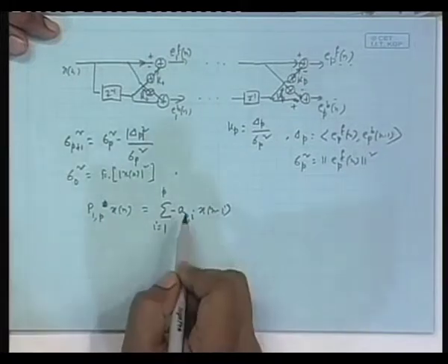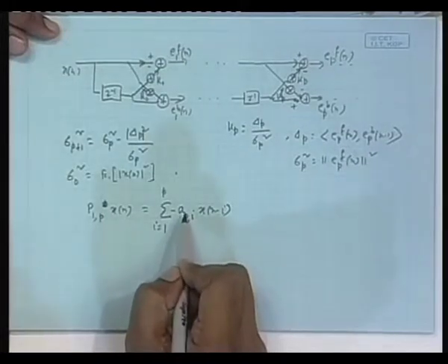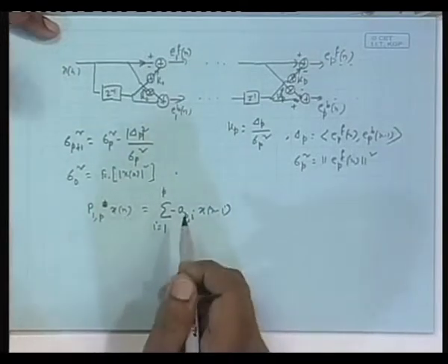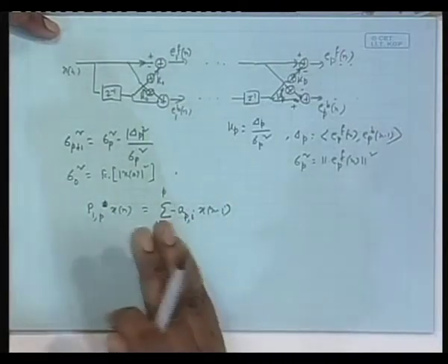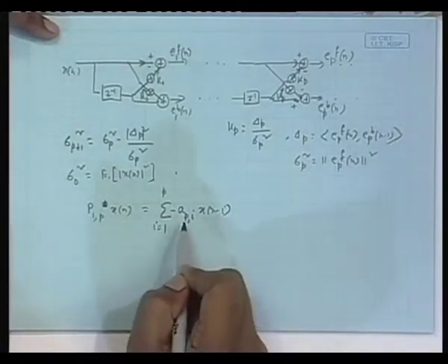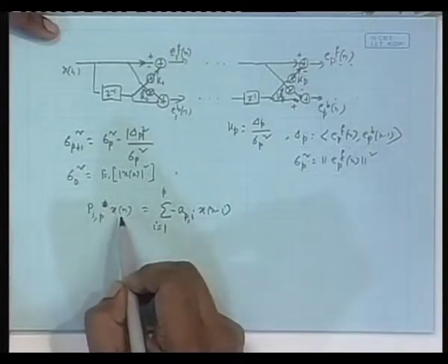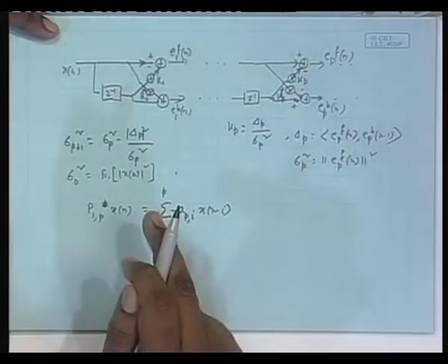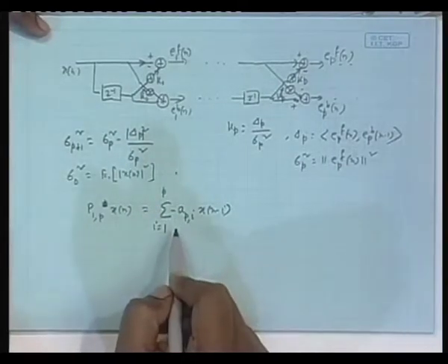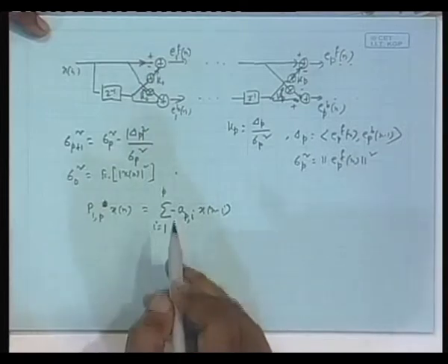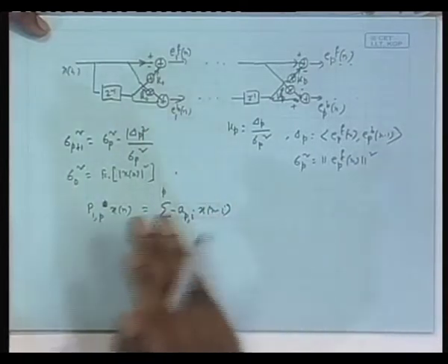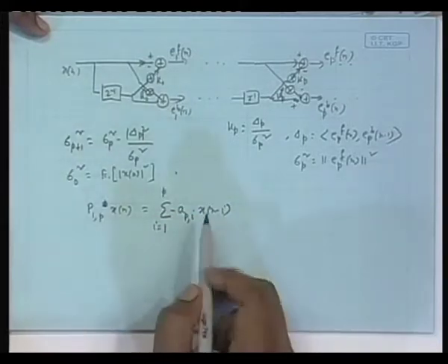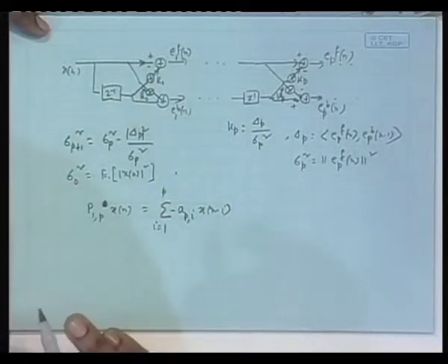Okay. These are also independent of n. The left hand side is a function of n, but n goes away simply because of our logic of stationarity. Remember that these are nothing but optimal filter coefficients after all. When you give x n as desired response and the x n minus 1 sequence as the input, obviously the filter coefficients will be given by these combiner coefficients because of stationarity. You know their exact values also, but I will not go for that calculation by R inverse p here. I will be recursively updating them. So, they are independent of n.